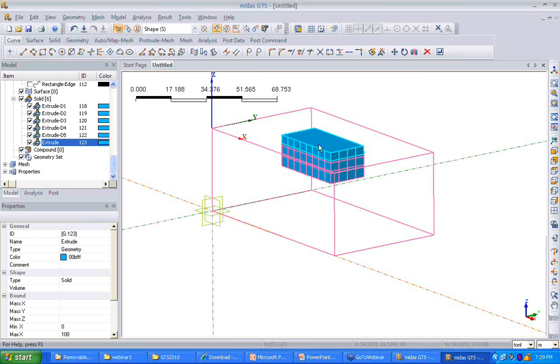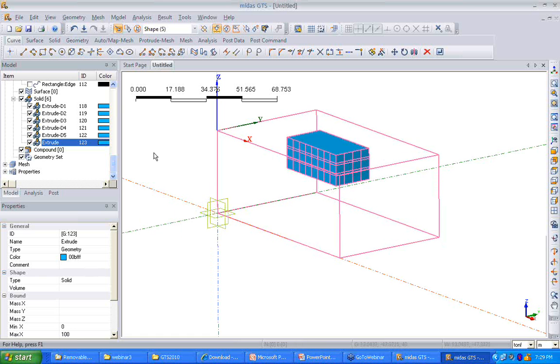We have only created the impression of those piles on the embedded solid, but we haven't actually modeled the piles. By modeling, I mean we haven't created 1D elements for the piles. We have just created the edges for the piles, and the impressions of those edges have been created on this excavated solid. So then let's move ahead with the meshing part.